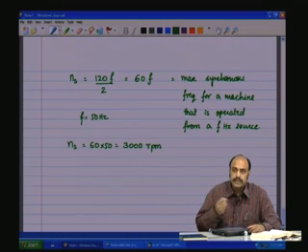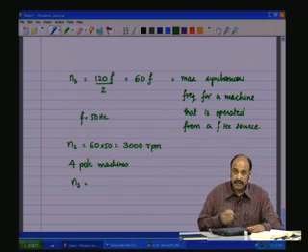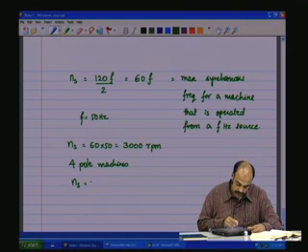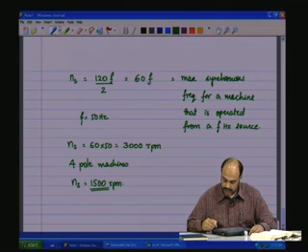And many of the machines which are there in the market are 4-pole machines, which means the Ns of all these 4-pole machines in our country is typically 1500 RPM, which will be on the nameplate. So keep that in mind.